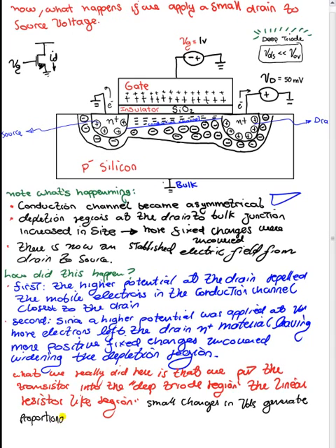So you could ask, is it possible to use the transistor in this region to simulate a resistor? The answer is yes, but there are some caveats, right? It's very hard because that region is very, very small as compared to, say, the saturation or just the triode region. So if you increase the drain to source voltage by a slightly higher amount, then you get out of that region and the transistor is not operating linearly anymore.